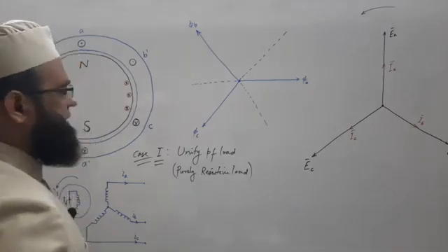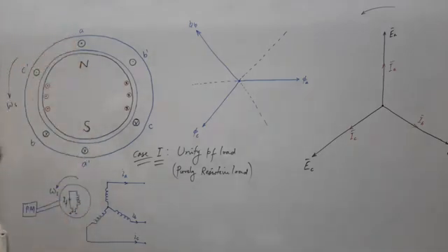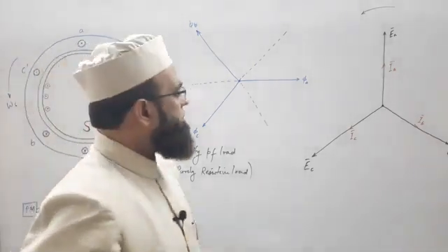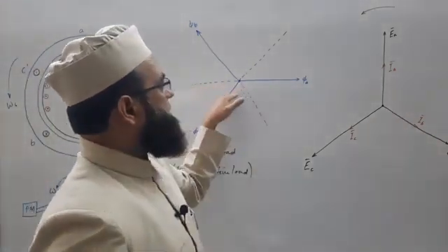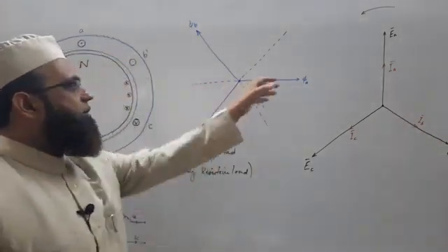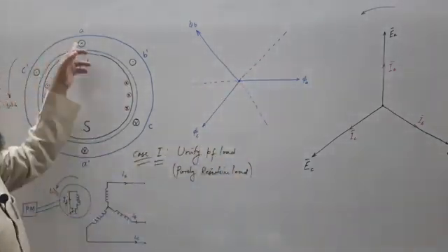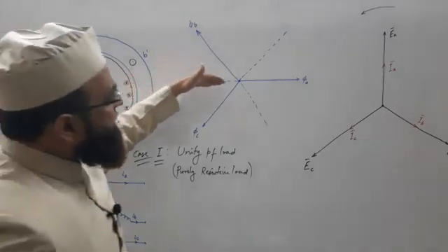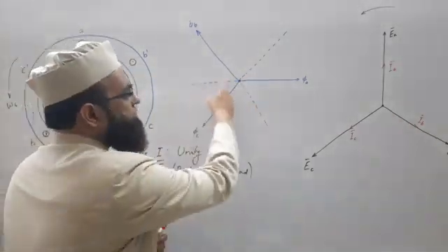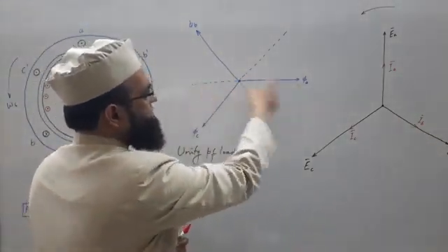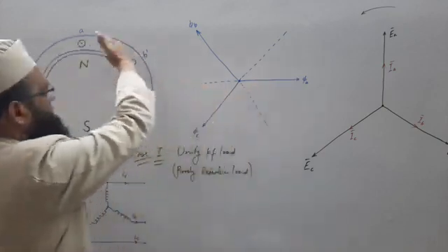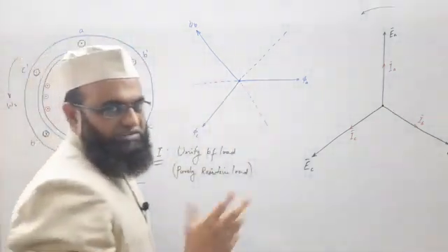As discussed earlier, when the current in a particular phase is 0, the corresponding flux is 0, aligned along its own axis. If IA is maximum, the corresponding flux will be maximum, meaning flux will oscillate along its own axis. See, the stator is stationary, so the axis will be fixed.